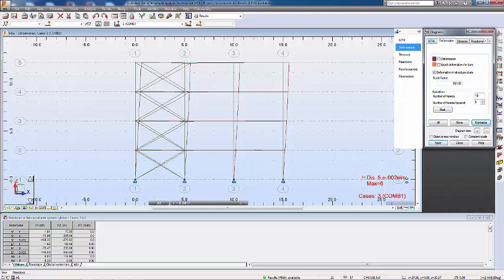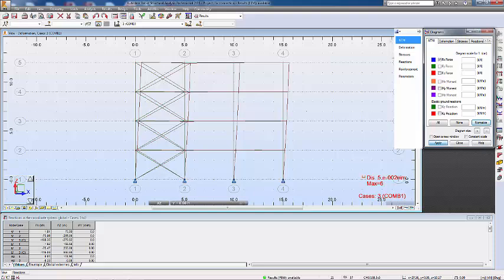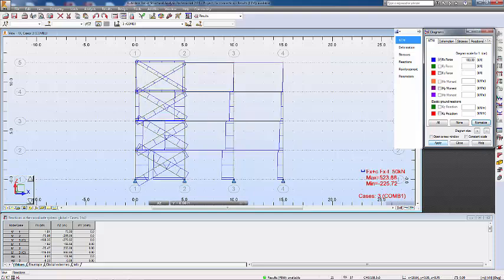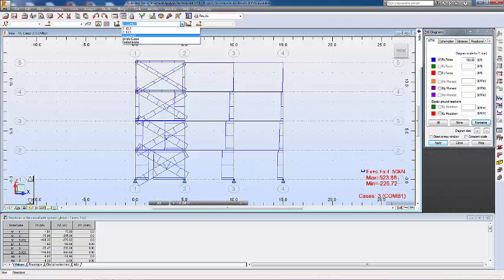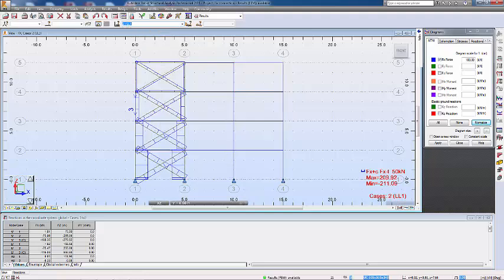Okay, so then the next one is the actual force. So let's have a look at the actual force, and then you can click on apply. If you have a look at the lateral loading, you may be surprised to see the lateral loading is actually accumulated in here when you subject it to the lateral loading applied on the side of the building.